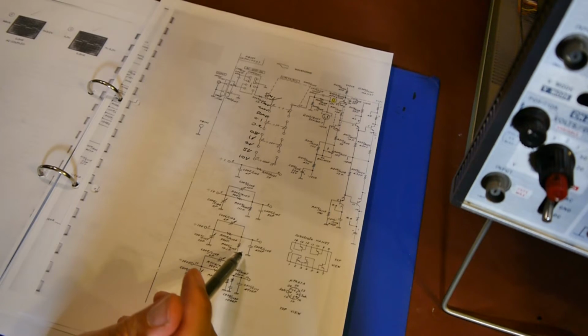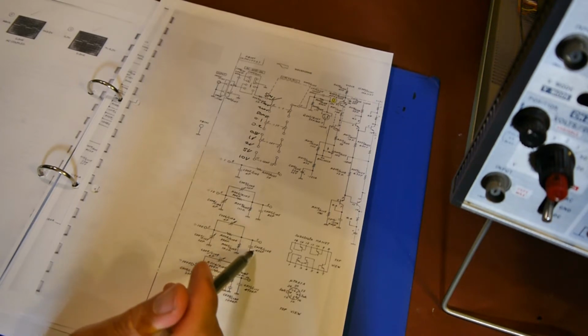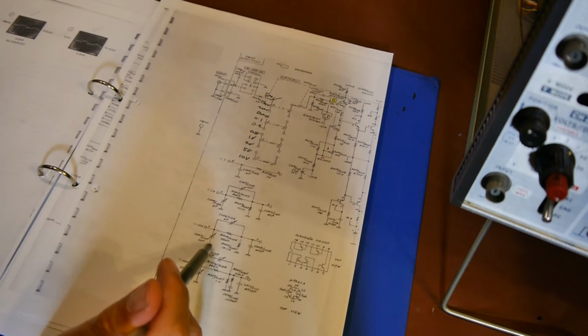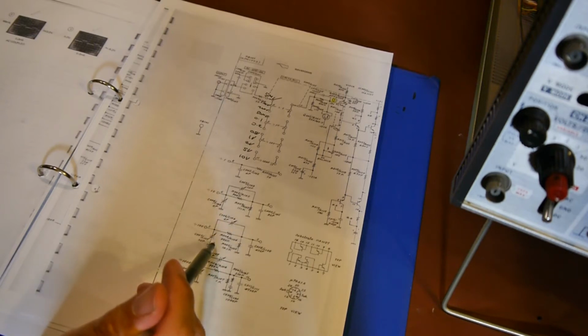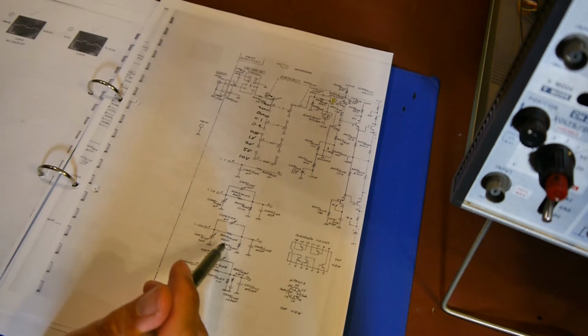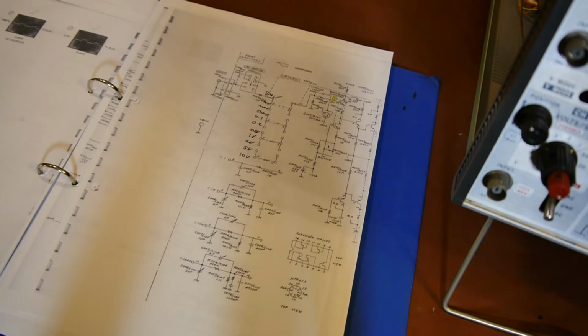The other things that we perhaps want to check for are short circuits in this capacitor here, C008, or maybe a short circuit in this variable trimmer capacitor, C007. Any of those could pull the input voltage down and make it not work properly. So I think it's worth checking that bit of the circuit out first.